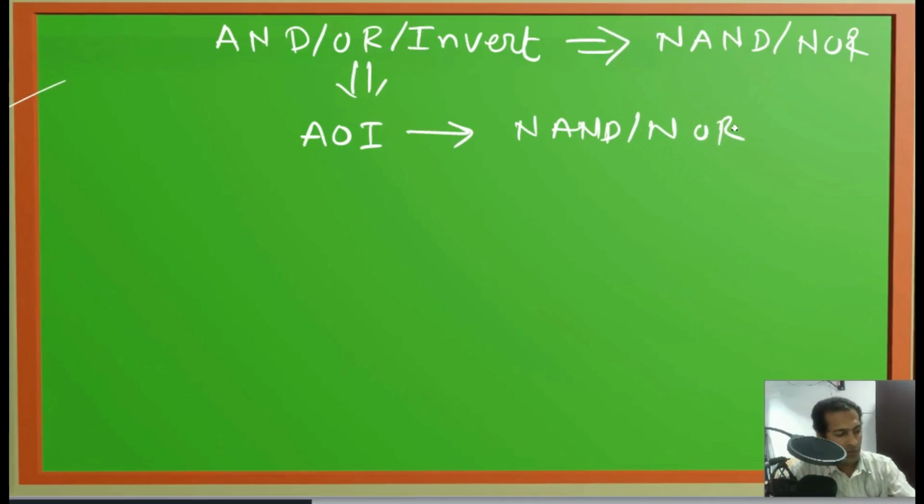In the design of digital circuits, the minimal Boolean expressions are usually obtained in SOP form or POS form. Sometimes the minimal expression may also be expressed in hybrid form. The SOP form is implemented using a group of AND gates whose outputs are ORed, and product of sum forms are implemented using a group of OR gates whose outputs are given to AND.